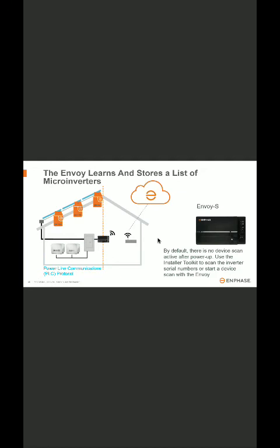So in case you are doing a replacement or you are adding something, then you have to run this scan again from your installer toolkit. Okay, because after commissioning, Envoy only talks to those devices which are there in the Envoy memory or Envoy system.